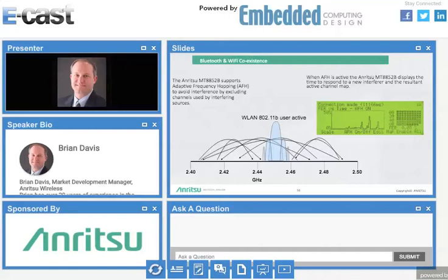Bluetooth and Wi-Fi coexistence. That's another key aspect, because they do share the exact same band in the 2.4 gigahertz area. So our equipment can do both Wi-Fi and Bluetooth, and we support adaptive frequency hopping. That's the way Bluetooth works: it hops around inside the band, looking for channels that have interferers. So it'll avoid those. It'll go back and check every once in a while to see if there are still interferers there. But this is your wireless LAN transmitting in the middle and your Bluetooth trying to hop around it.